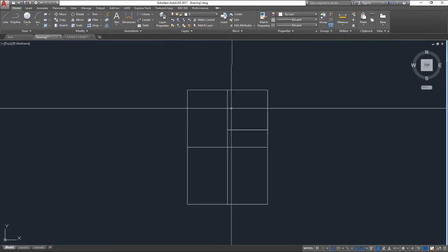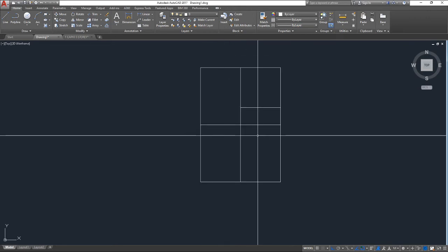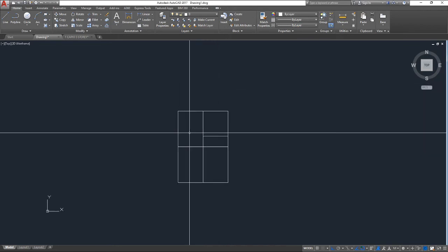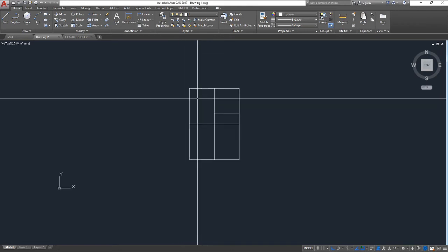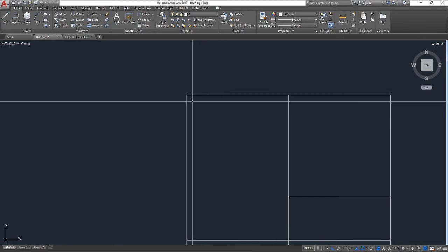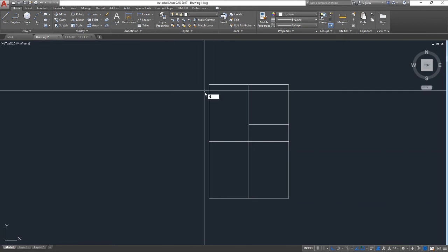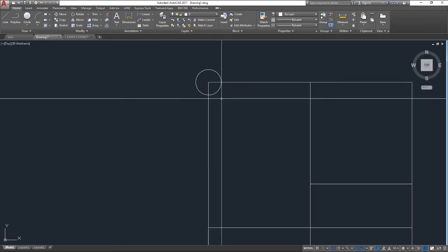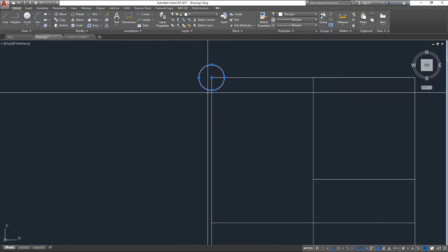Next, after you draw your column framing plan and beam framing plan, let's take this point as 0, 0, because in STAAD.Pro it will read where your point 0, 0 is. So to do that, you need to identify the 0 coordinates in AUTOCAD. So simply draw a circle here, and then for you to know its coordinates, you need to know its properties.